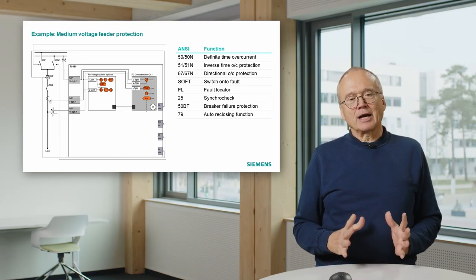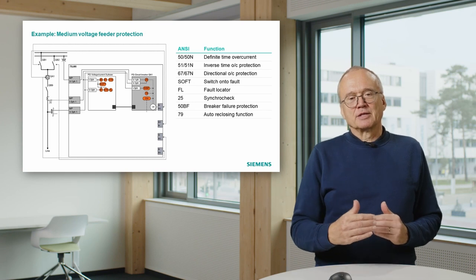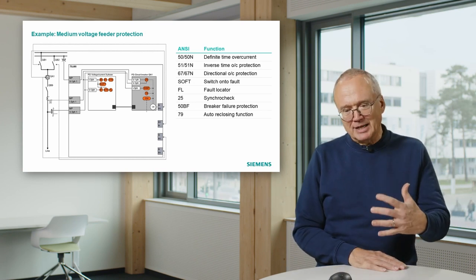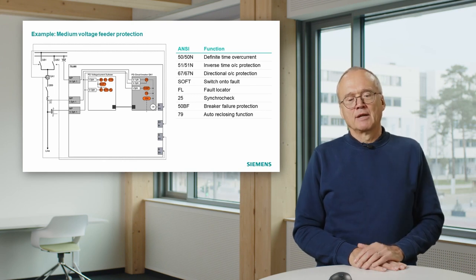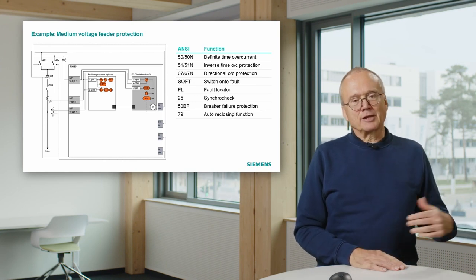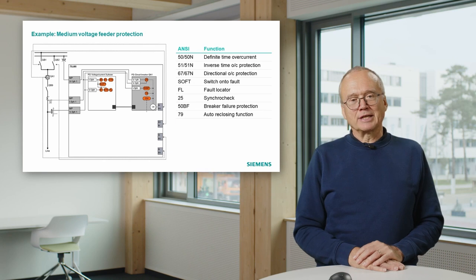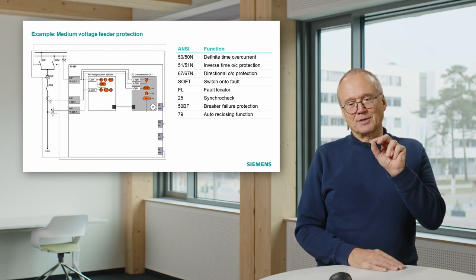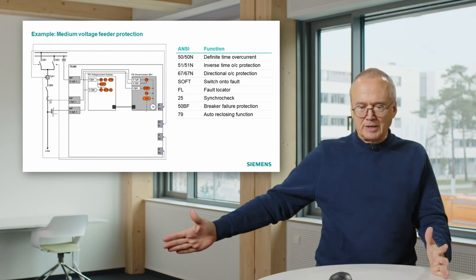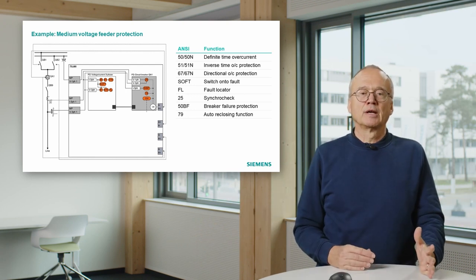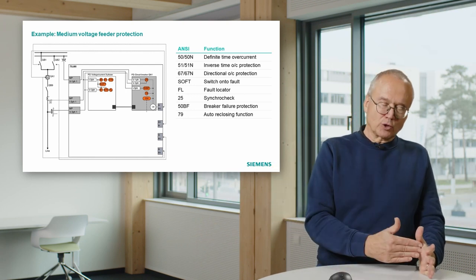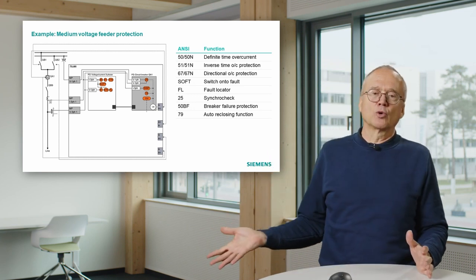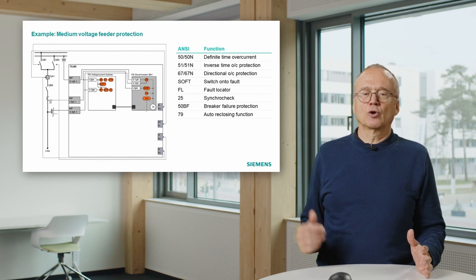As I already described, you often have some delays. You need delays in overcurrent protection to get selectivity. That means especially at the beginning of the feeders you have long delay times. And this particular function addresses the situation where you have the whole feeder out of operation, and now you reconnect the feeder and somebody forgot to remove an earthing switch or whatever.